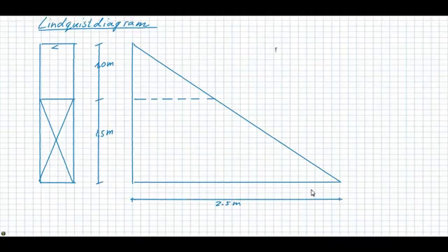The moment we start operating the filter, there is a hydraulic resistance and we will measure a pressure drop over the filter. This is called the clean bed resistance and can be calculated by the Carman-Kozeny equation. The smaller the grain size, the higher the flow velocity, and the lower the temperature, the more the resistance is.